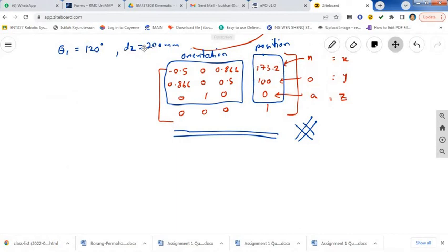And also when your arm extends or retracts, you will get the new coordinate. So with a combination of these two, you will get a new coordinate. So you always track your coordinate, where the position of your gripper is, referring to your world reference frame based on this matrix. This matrix you will put into your robot controller.